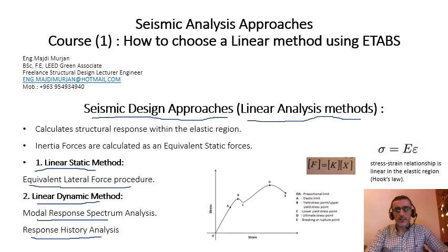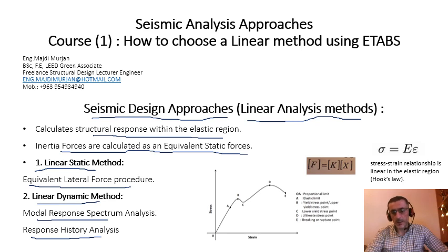During this analysis, the linear analysis methods, we calculate the structural response within the elastic region. Inertia forces are calculated as equivalent static forces. Here we can see F equals K times X, stiffness multiplied by displacement, and every response will be in this region, the elastic region.